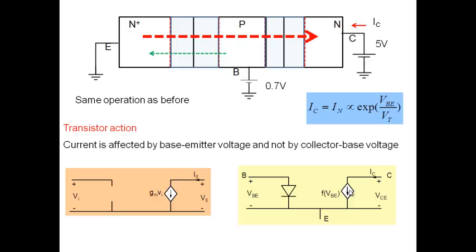Okay, but remember what kind of a voltage controlled current source we wanted? We wanted an I0 which is linearly related to Vi. Linear relationship. I0 is equal to Gm times Vi here. We wanted a linear relationship. Well, IC is not linearly related to base emitter voltage. IC is related to base emitter voltage in an exponential manner here.